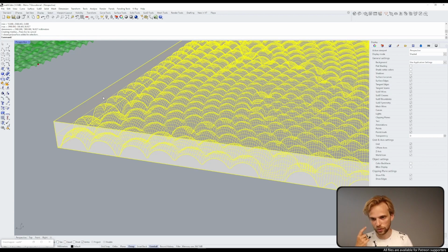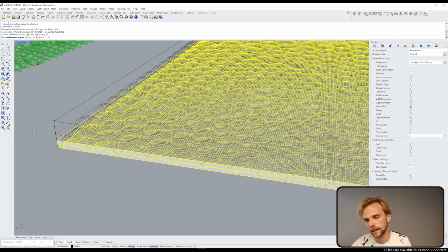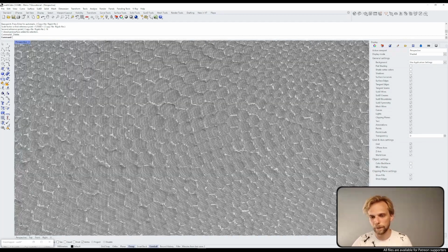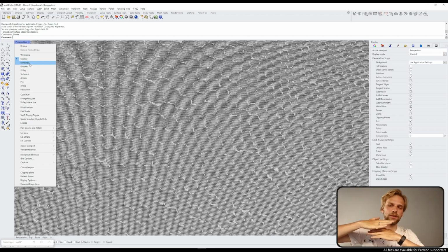So I do need to create a bounding box for it and scale in 1D the form together with the bounding box to something like 16 millimeters, so that it doesn't force us to glue a bunch of MDF boards on top of each other and then deal with the seams, which is very obnoxious and very annoying to deal with.